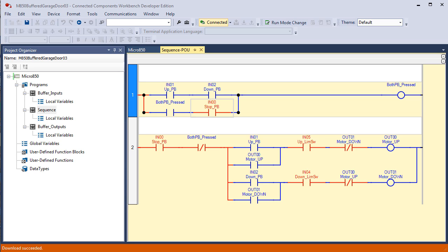That kind of stuff, I've seen operators doing it. You can't eliminate everything, but you could see that this logic does not only stop the garage door from moving if you press both buttons, but it won't start again until you clear it by stopping what you started, in a sense. We kind of started this section with get skinny, meaning to make the control rungs, rung 2, as skinny as possible to make it easy to read.